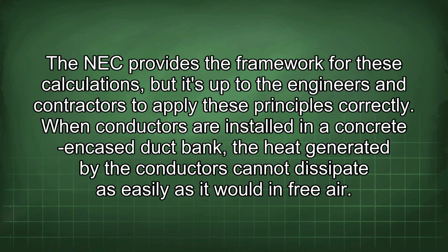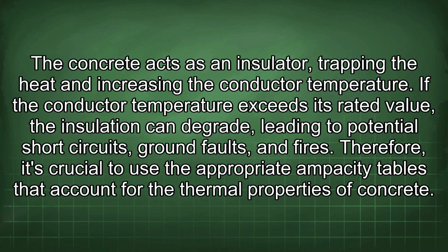correctly. When conductors are installed in a concrete-encased duct bank, the heat generated by the conductors cannot dissipate as easily as it would in free air. The concrete acts as an insulator, trapping the heat and increasing the conductor temperature. If the conductor temperature exceeds its rated value, the insulation can degrade, leading to potential short circuits, ground faults, and fires. Therefore, it's crucial to use the appropriate ampacity tables that account for the thermal properties of concrete.